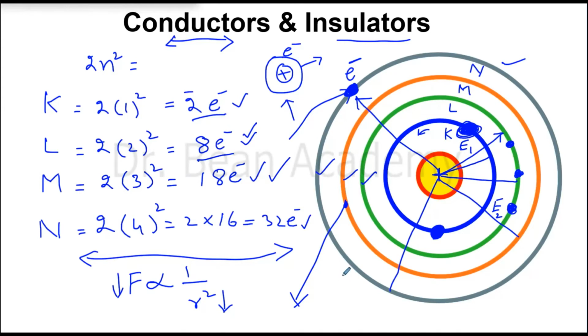So those materials which have partially filled outermost shells are good conductors, and those materials which have completely filled outermost shells are the candidates for good insulators. And the electrons in each shell are considered to be at a certain energy level, E3 for the third and E4 for the fourth, and this is the energy I need to kick that electron out of its orbit.